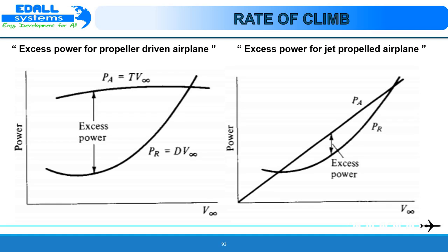To see this more clearly, consider an aeroplane with weight 2,275 kg, a wing area of 30 meters squared, parasitic drag coefficient of 0.015, Oswald efficiency of 0.6 and aspect ratio of 6. If the velocity V infinity equals 150 meters per second at sea level, and if the aeroplane is in level flight, then the drag coefficient equals 0.0175.